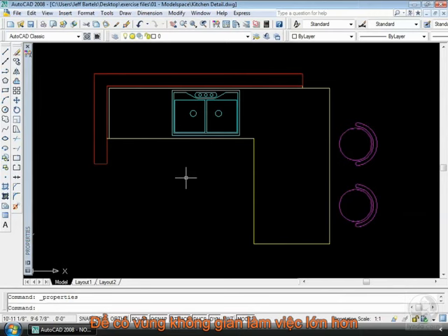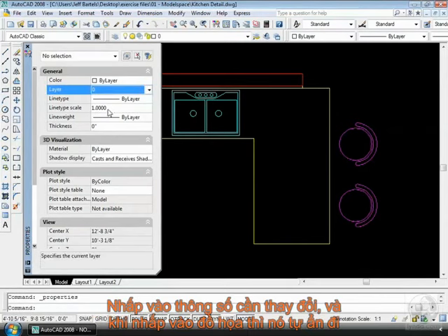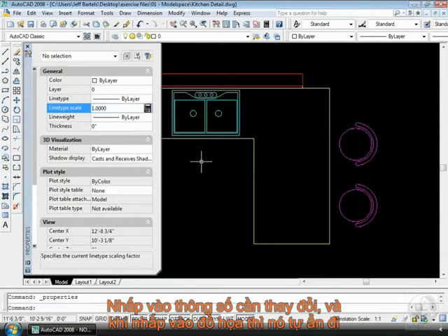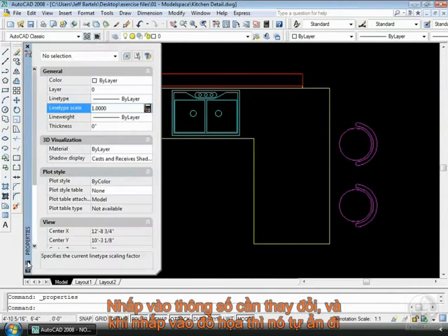If I wish to use my palette at this point, all I have to do is hover over the mast, the palette will open up, and I can click and do my changes, do whatever business I have to, and if I move off of the palette, it will return to the collapsed state. If I need the palette to stay open for any length of time, I'm going to come down and click on the Auto Hide button once again, and that will lock the palette open.